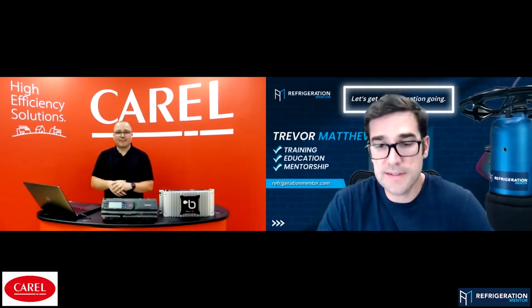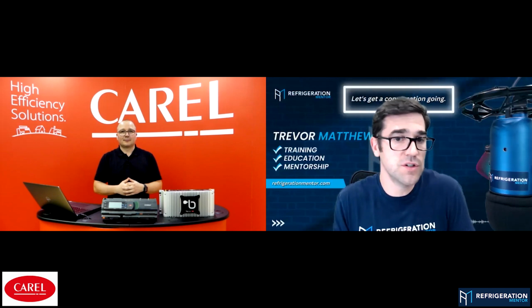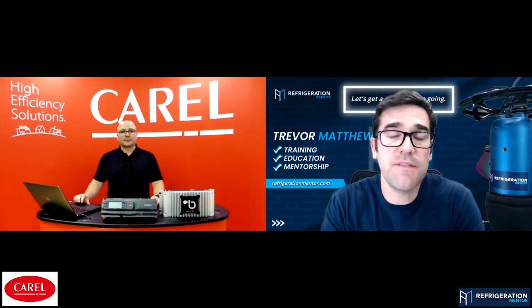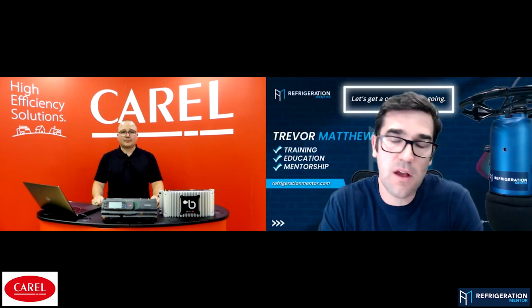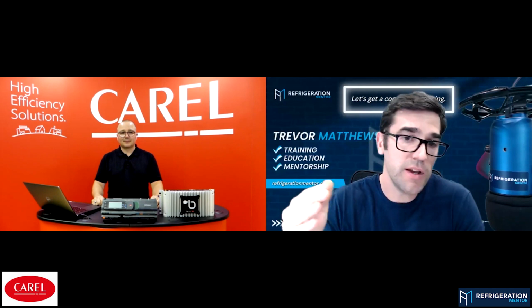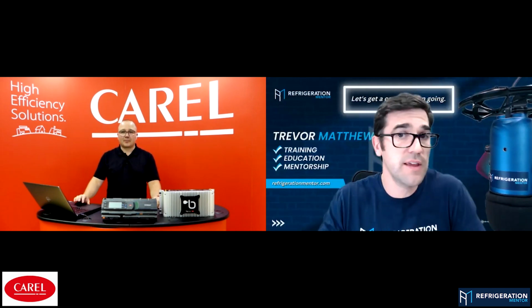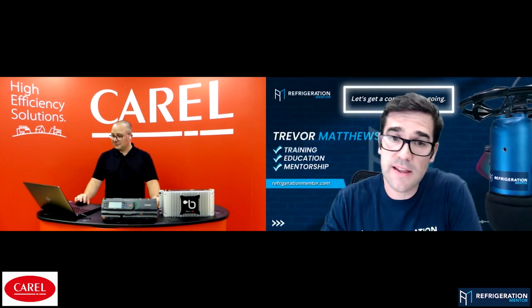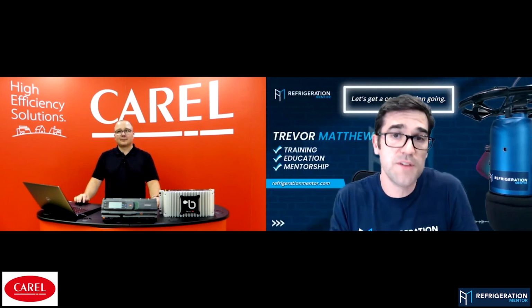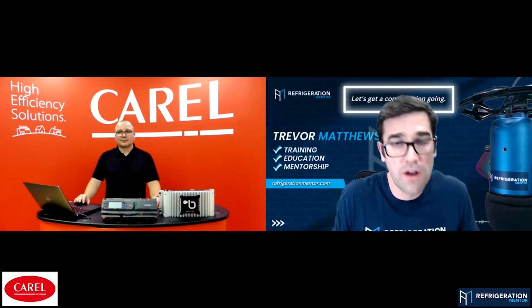And the easiest thing, for anyone out there who works on anybody's rack, is you just pump down that rack. The manufacturers of that equipment, all the big manufacturers, design them good. They do a great job. Just like you're working on a standard refrigeration rack, you pump it down the same way. You shut the liquid outlet, and then your flash tank receiver should start to fill up. And then you should start to hear the compressors cycle off, because you're draining the whole floor of all the refrigerant.